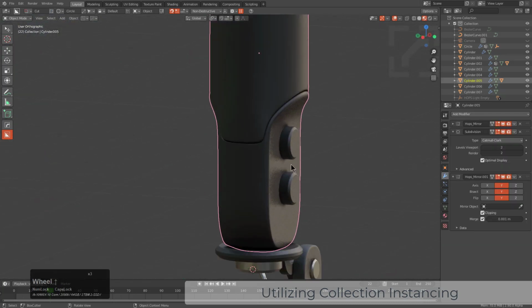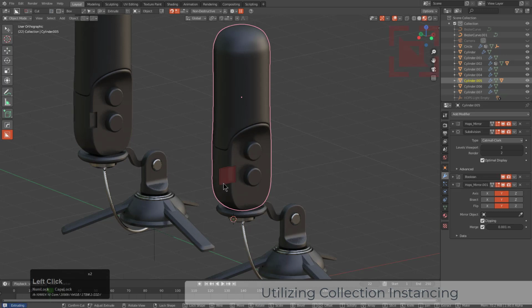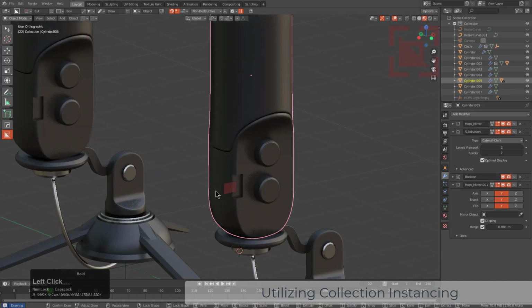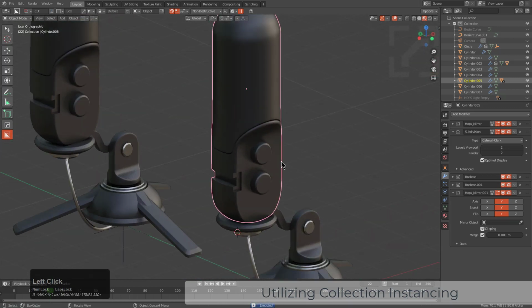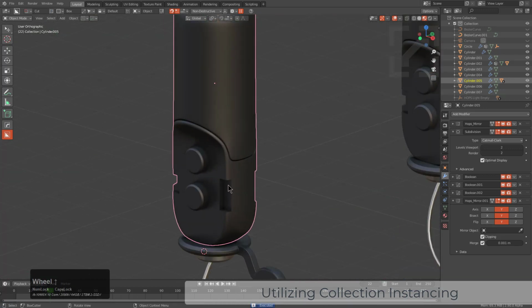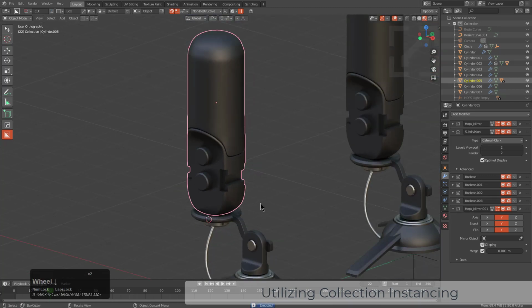And if we select this piece and go to town on it, these changes will of course take place on the other side. I'll just perform a quick box cut, but we see that we're able to work on multiple meshes at the same time, which is basically an easier way to work across meshes that have linked data than dealing with linked duplicates, which can be a little bit limited. So I just wanted to stress on that as well within this video.